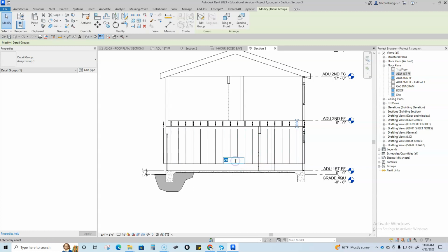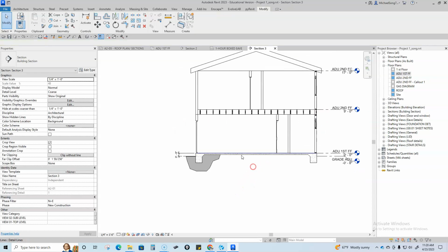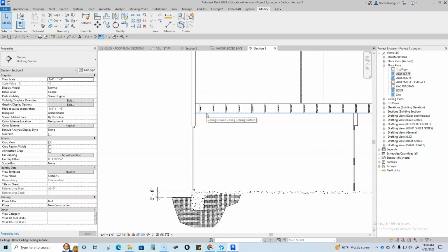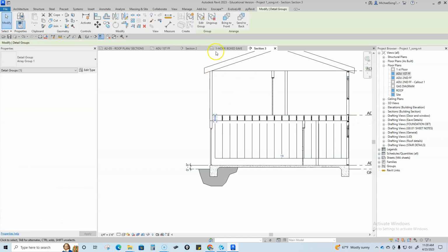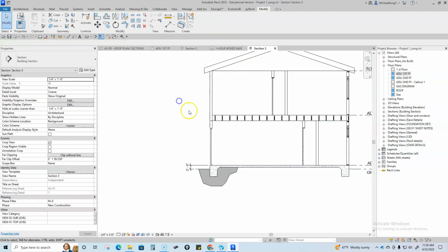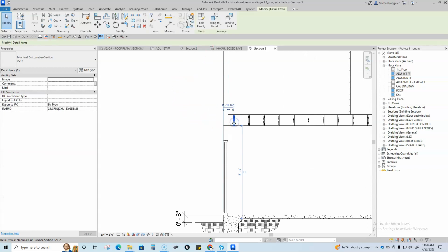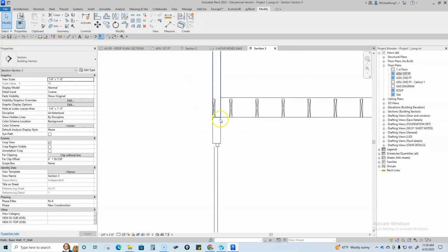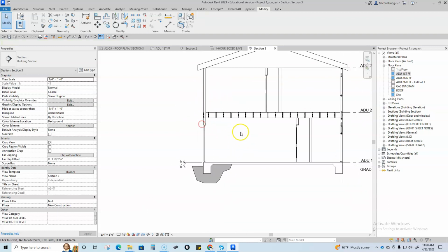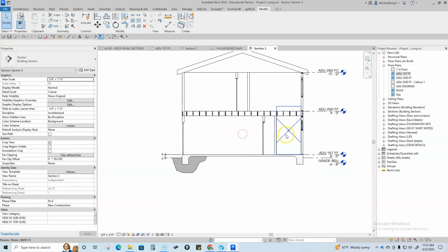And then you click that and go 19. And that's fine. Not virtually every house that you design is going to fall on a 16-inch module, and that's not a big deal. So I'm just going to ungroup that. I'm going to copy that, CC, and you'll just have one that is a little bit closer. So that's totally acceptable, guys.